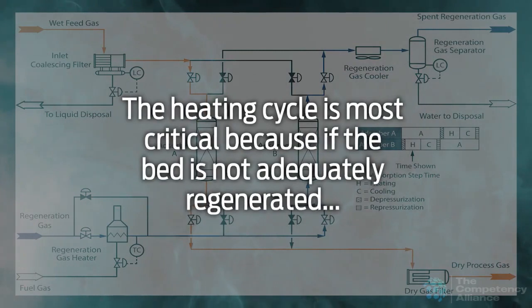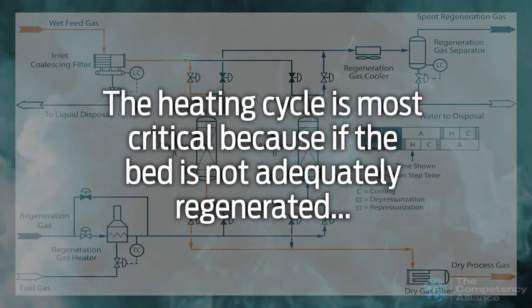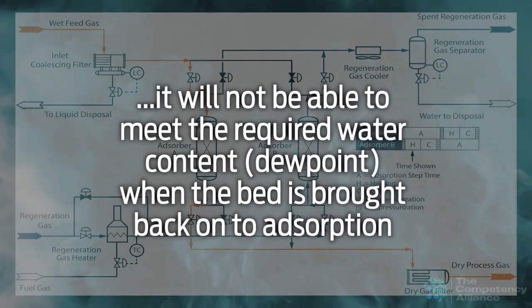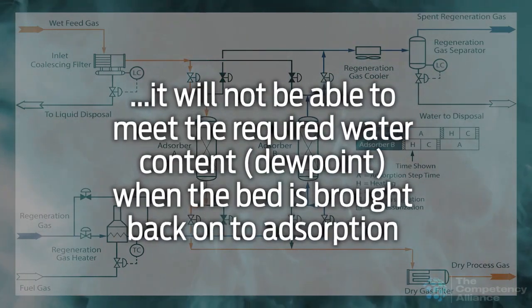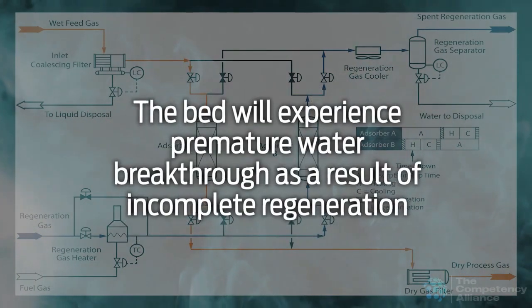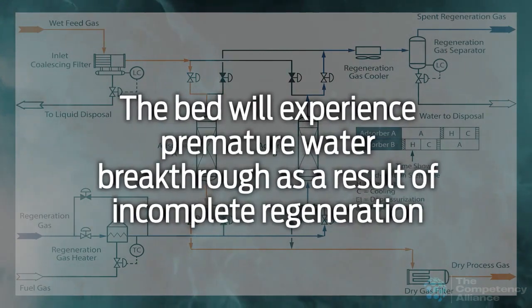The heating cycle is most critical because if the bed is not adequately regenerated, it will not be able to meet the required water content, dew point, when the bed is brought back on to adsorption. The bed will experience premature water breakthrough as a result of incomplete regeneration.